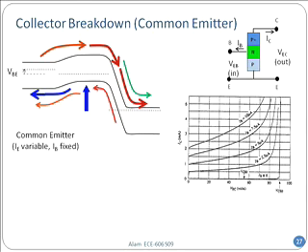Very soon, because of the presence of that first barrier, the first PN diode, the breakdown will occur very quickly. You can see on the right-hand side how much faster. It almost begins to break down at a very low voltage. Even by 20 volts, the currents are gradually increasing quite a bit.